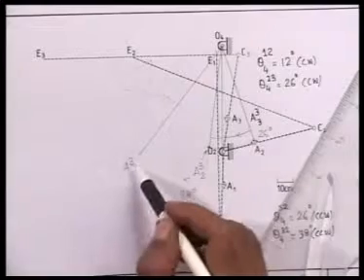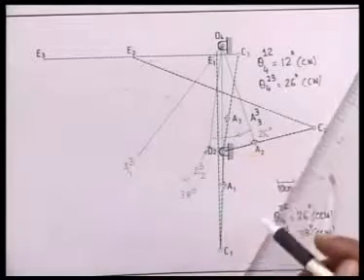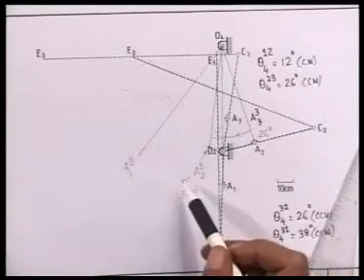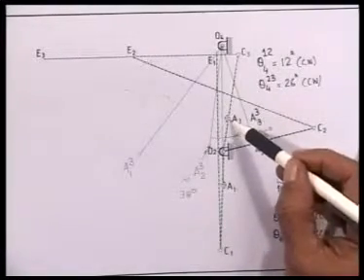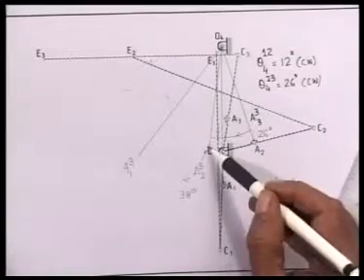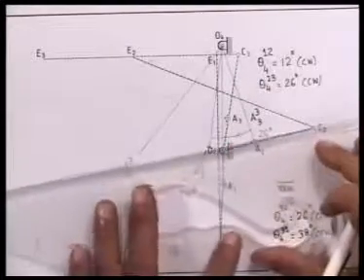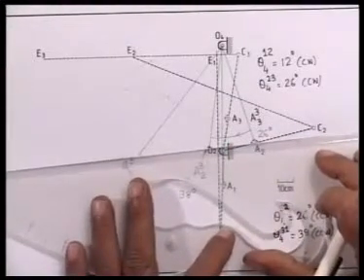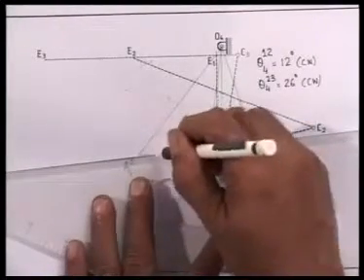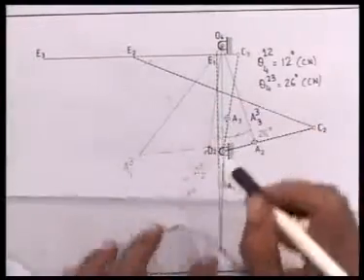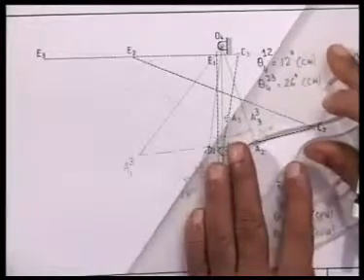because it is inverted on the third position of O4B, and the rigid link AB is of constant length. So the center of the circle passing through these three inverted positions, namely A3, which is A33, A23, which is here, and A13, we determine in the usual manner. We draw the perpendicular bisector of these 2 lines, namely A23 and A13, and A33 and A23, that is this line.